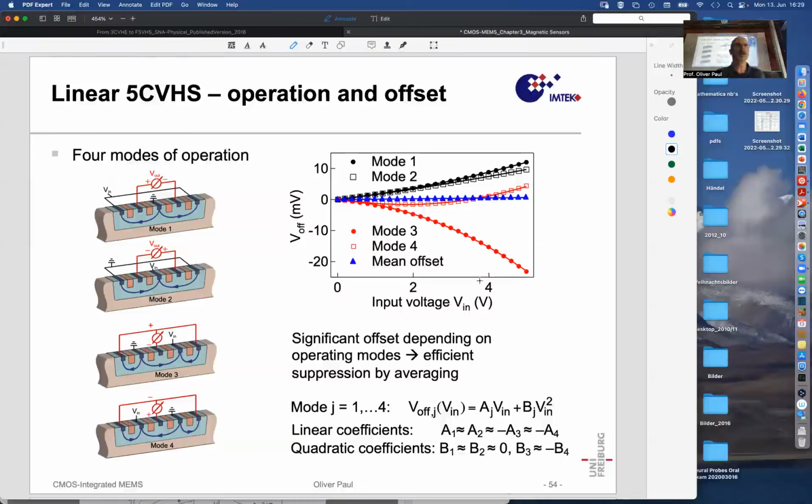But if I average them, as I should do in current rotation, they almost eliminate. They almost cancel. I mean, you can't even see that they don't cancel, but they don't cancel completely. And what remains uncancelled is still pretty large. We're talking about millivolts here. So even if it's a tenth of a millivolt, 100 microvolts, still a large offset.